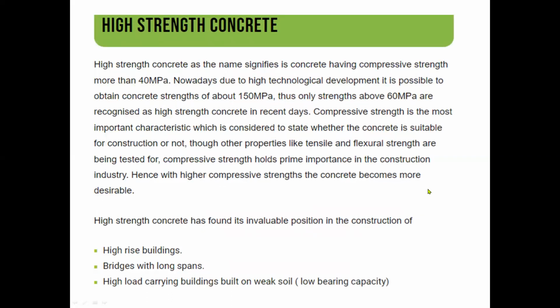High-strength concrete, as the name signifies, is concrete having compressive strength more than 40 megapascal. Nowadays, due to high technological development, it is possible to obtain concrete strengths of about 150 megapascal. Thus, only strengths above 60 megapascal are recognized as high-strength concrete in recent days.